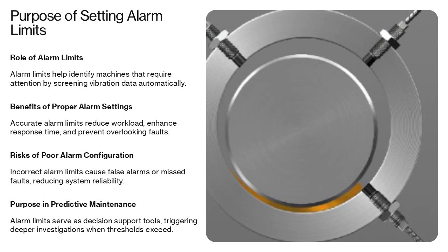Correctly configured alarm limits allow software systems to automatically screen incoming data and generate exception reports, highlighting only those assets that deviate from expected behavior. This approach dramatically reduces analysis workload, improves response time, and ensures that developing faults are not overlooked.